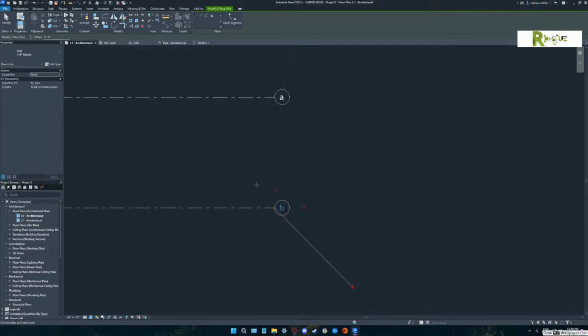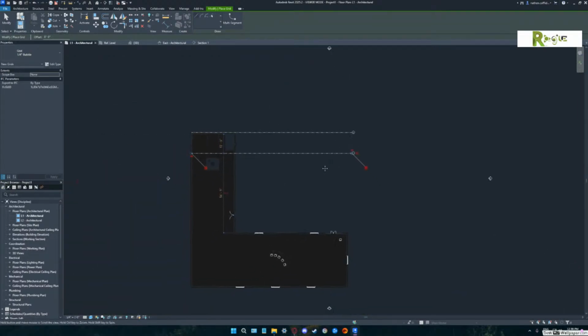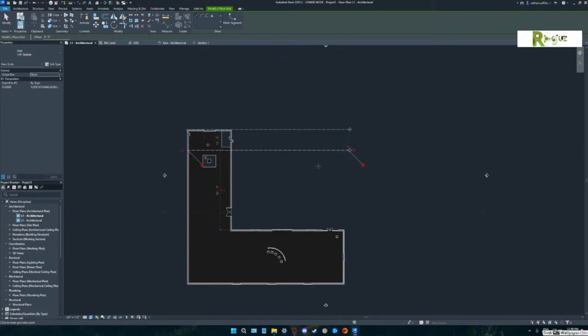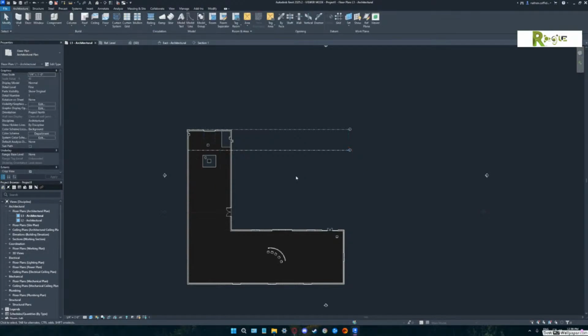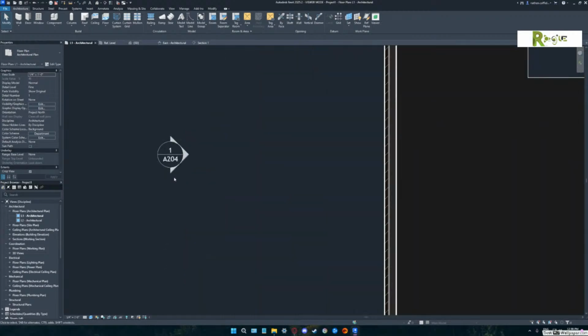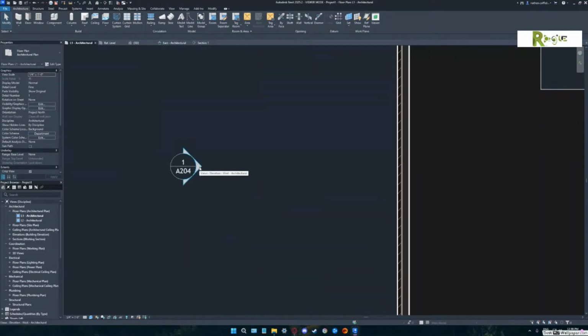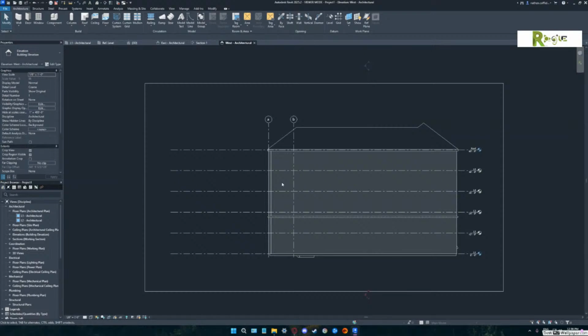But more importantly than any of that is if we go to our east or west elevation, because we will see those column lines in our east or west. If you hit escape, and go to one of those side elevations, double click on it. You don't have to zoom in. You'll be able to double click on it. You see those A and B are automatically showing up. You see how it went higher than the building?